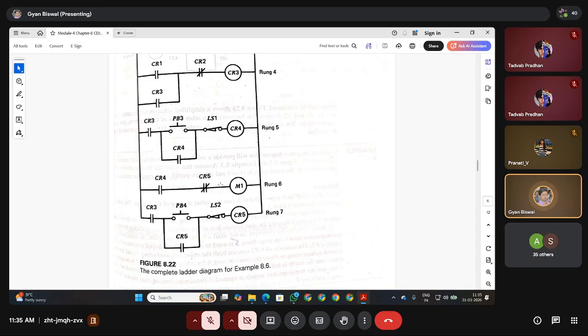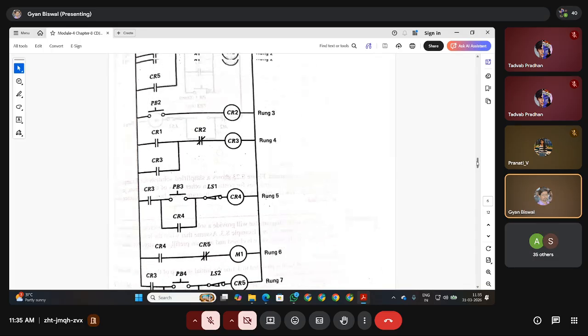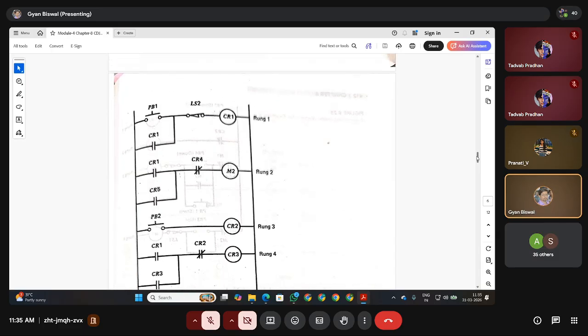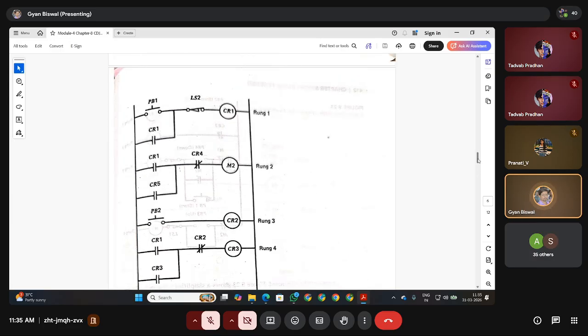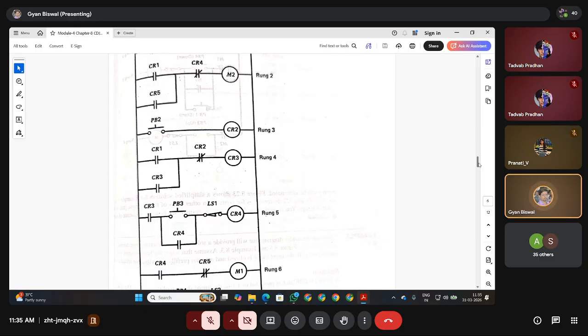Okay. Now, in this scenario, what was CR2 handling? CR2 is the stop operation, most important, so that should remain closed here. In fact, better programmers always keep it so. Here, for your purpose only, we started with the stop operation. But a good automation engineer will always think about how to stop the operation in case of emergency without any damage. So we will always keep CR2 first, in normally closed condition. Then I will draw CR1 normally open and keep CR3 here. Theoretically, both approaches are the same. Practically, the essence is different. Okay?